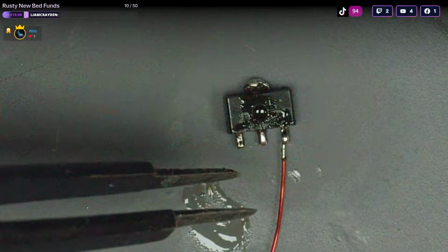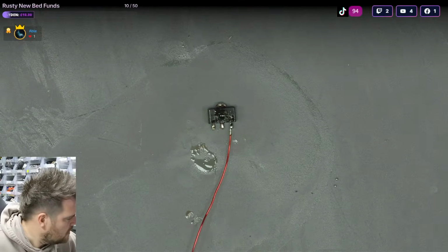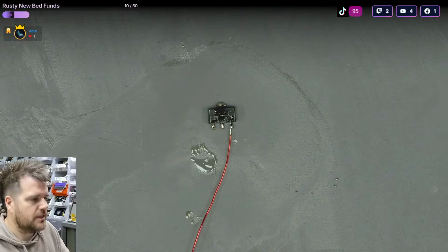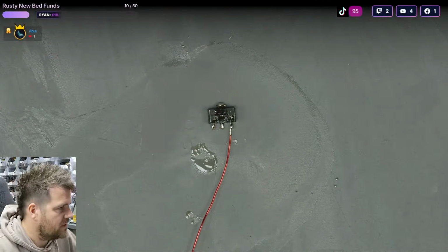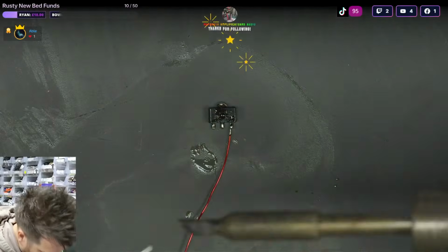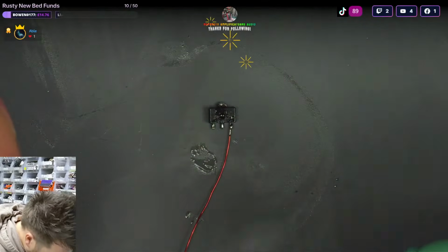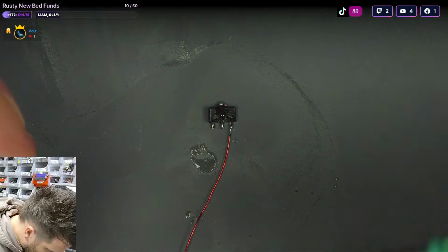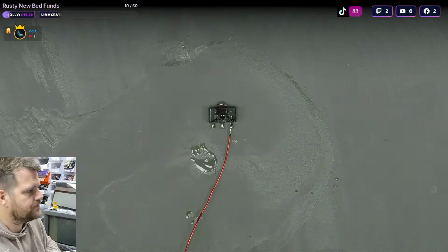But you saw how difficult it was to attach without the board being clean. So that's why we really got to. It takes a lot more work once you're working on a board with electrolyte rot. Everything's a lot harder. Components rot, pins don't stick, pads rip. This is why you want to do the recap really before it actually happens, because it makes everything else harder.